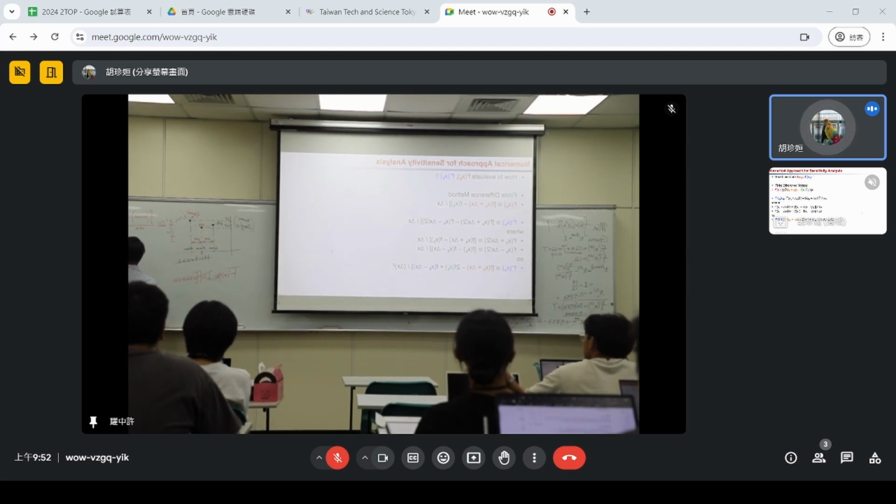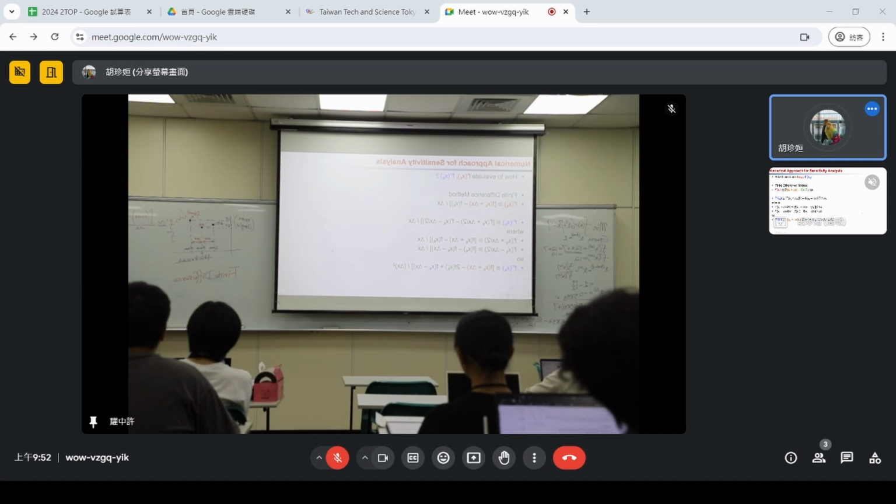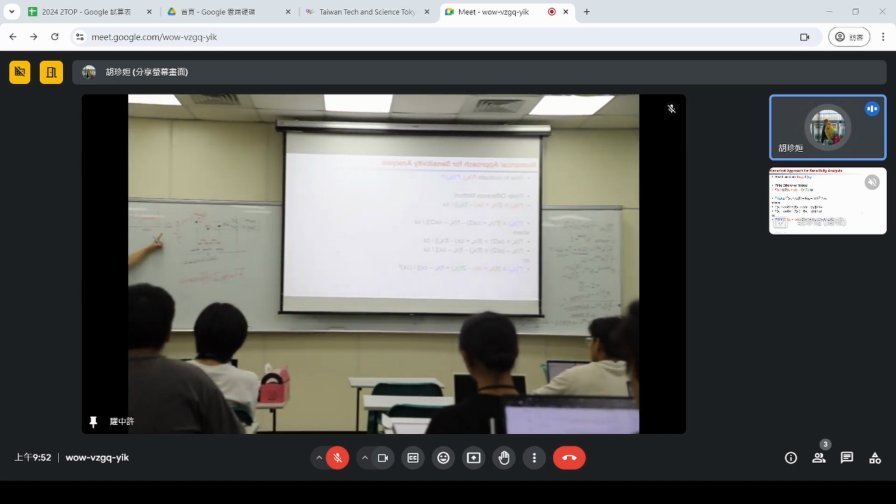So you will have a slope of degree over millimeter. So for every increment of 1 millimeter, my bending angle increased by 5 degrees. That's the slope. That's your first order derivative.